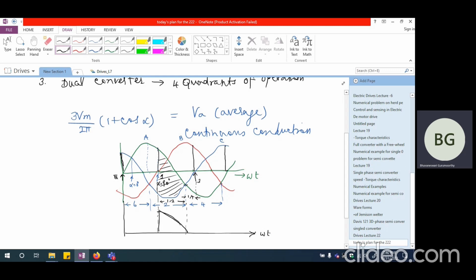So this is going to be the sinusoid, which starts from its peak value and goes down to 0 magnitude. So this is the complete quarter cycle of VAC. So this is alpha, and this is going to be alpha plus pi by 2. And from there, for another 30 degrees, you're going to have 0 voltage.